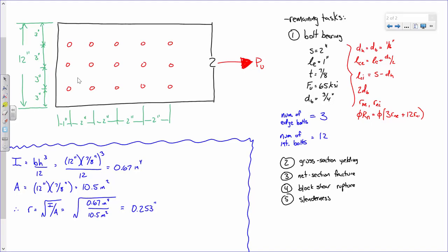What do you mean, what about? Like if you're taking a W, you have to go find the x-bar, but you have to go to the equivalent WT. How do you do the moment of inertia? You don't have to. Look it up, it's right there. The only time you ever need to go through this exercise is for something like a plate. Everything else, all the r values and the I values and the A values, are all looked up, or they're all there.